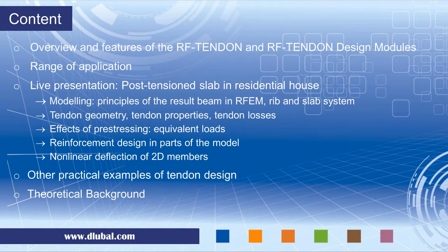Hello, everybody. I would like to give you an overview of the features of our modules for tendon design, of pre-stressing design in RFEM. I will start with a short introduction to show the range of the application, and then we will switch into live presentation of how we can design a post-tension slab in a residential house. We will start with the modeling in RFEM. I will explain the principles of so-called result beams and the system rib and slab. And then I will switch into an external module to show the tendon geometry, properties, losses, the effects of pre-stressing, and also some reinforcement design.